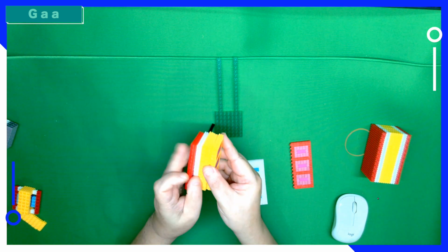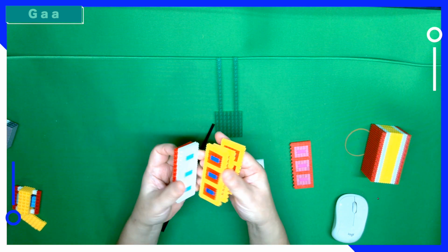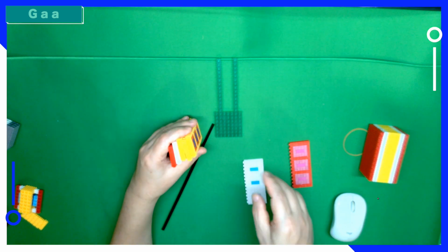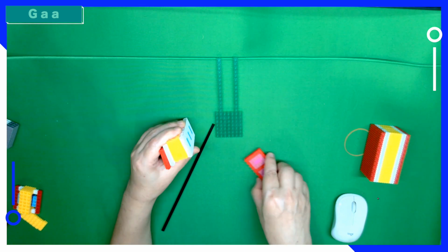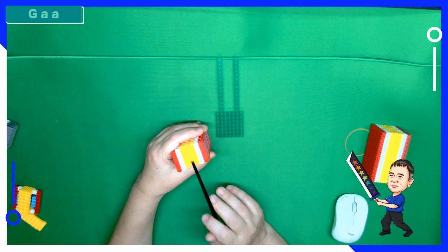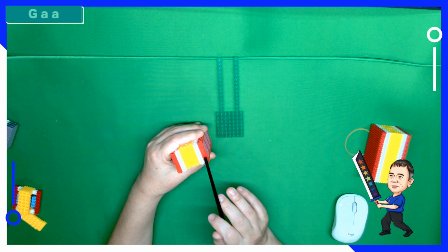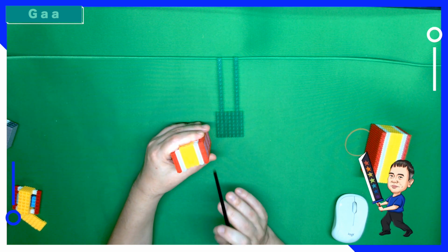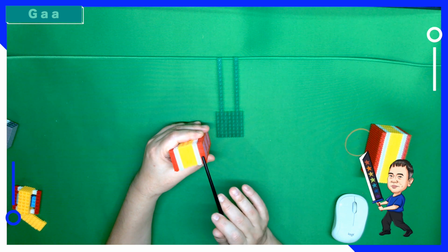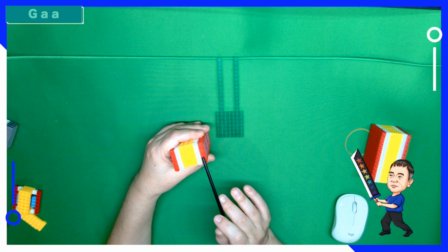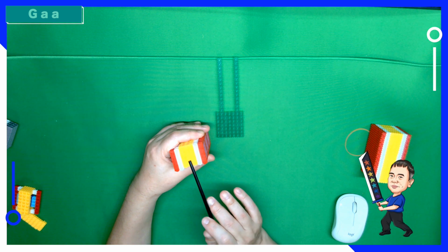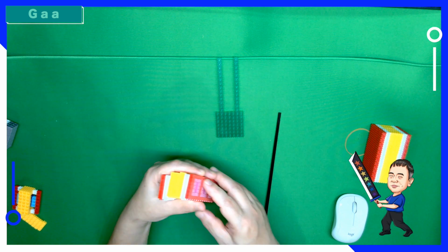And there are totally three bridges. I slice it down so you can see there are three bridges in this place, and all connecting between the source and the drain. Now notice one thing. This is a gate, right? The yellow part is the gate. Between the gate and the source or drain, there is an oxide layer, an insulating layer, because the current is not allowed to flow between the source or drain to the gate. So the oxide layer is in between.